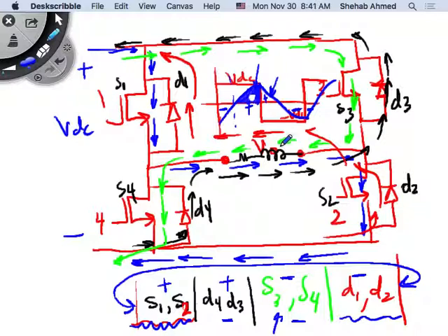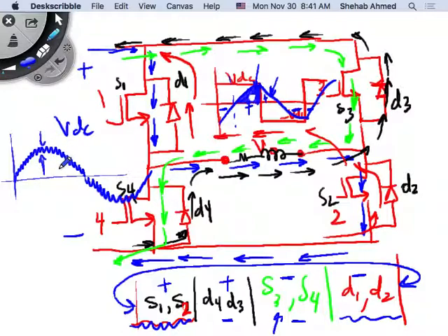But in the case of multiple switchings per cycle, we want to create a sine wave. Here, is the output current a sine wave? It's not a sine wave. It's a highly distorted waveform that we really don't like, but it's an AC waveform. So if you have an AC motor that you plug across this voltage and current waveform, it will run, no problem. But what we want to get to is something that looks like a sine wave, and we will be switching multiple times per period and creating something very close to a sine wave. Sure, in that case, if we want to maintain the ripple low, the inductance is something that we can add to maintain lower ripple, yes, sure.